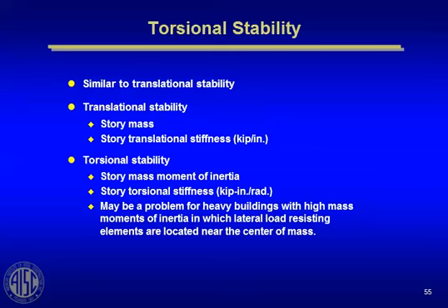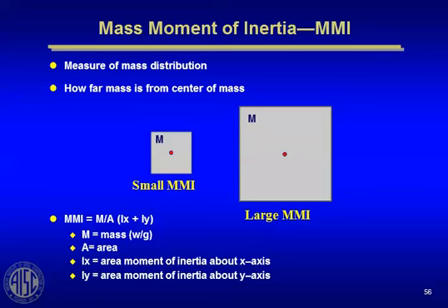There have been many buildings during earthquakes that have suffered severe damage due to a torsional instability, because the structural engineer put all the lateral load resistance in the core and put nothing around the perimeter. The earthquake came and it got the building rotating in a torsional manner and created a little bit of a torsional instability that overloaded the frame and caused failure or damage.